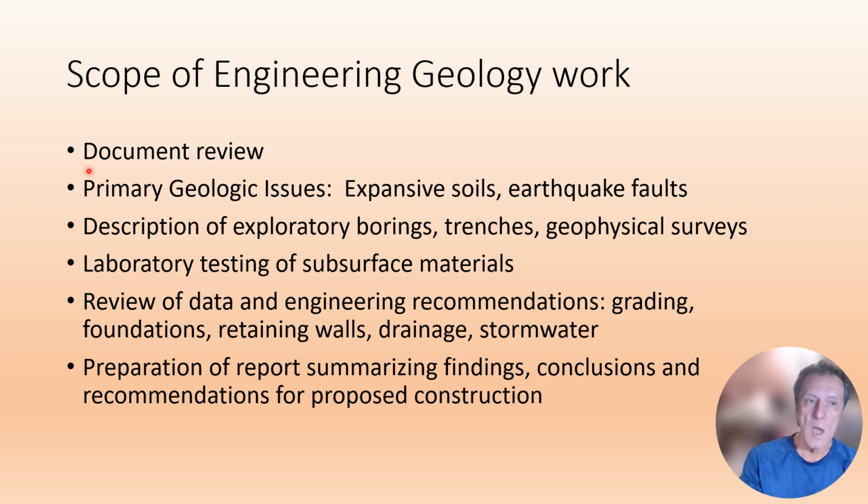You want to review those documents. You want to have, again, an idea of the primary geologic issues which will affect development of the site, including, are there expansive clay soils? Are there nearby earthquake faults or earthquake faults underneath the site? You want to get an idea of that.